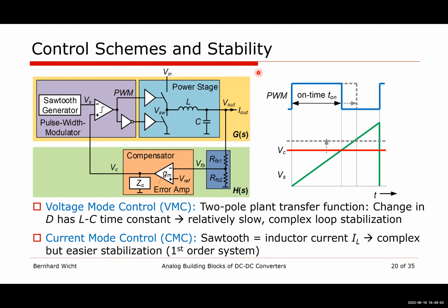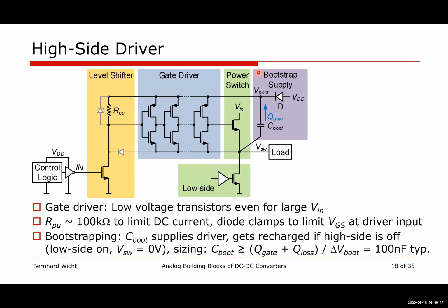Excuse me? Sure. This is Michael from Intel. A question regarding the power stage. You did not address parasitics on the power path, and frequently we have significant inductances on VSS or on VCC nodes, and then every switching causes very significant L di/dt noise, and through Miller goes to the driver, etc. Do you have anything that you do to cover it, or are you just trying to minimize it layout-wise?